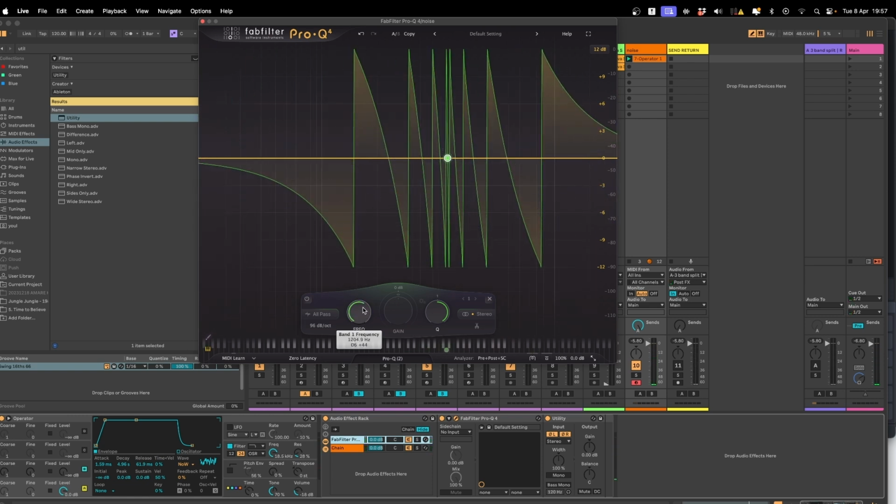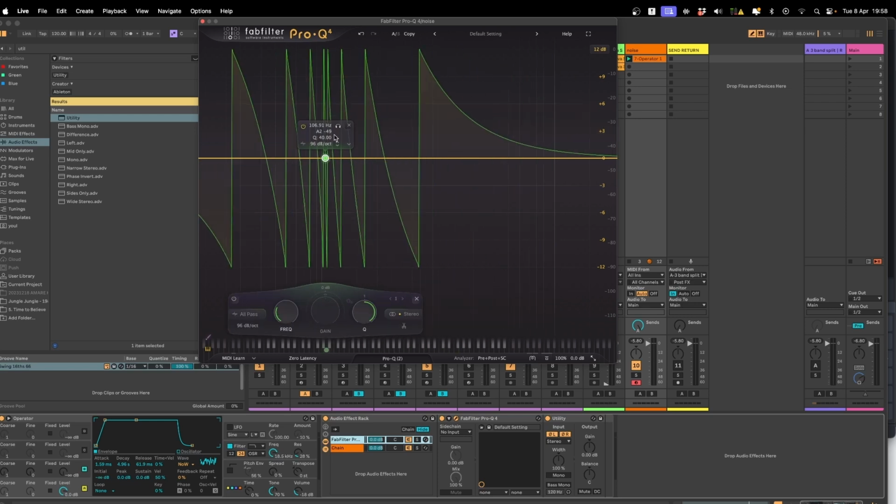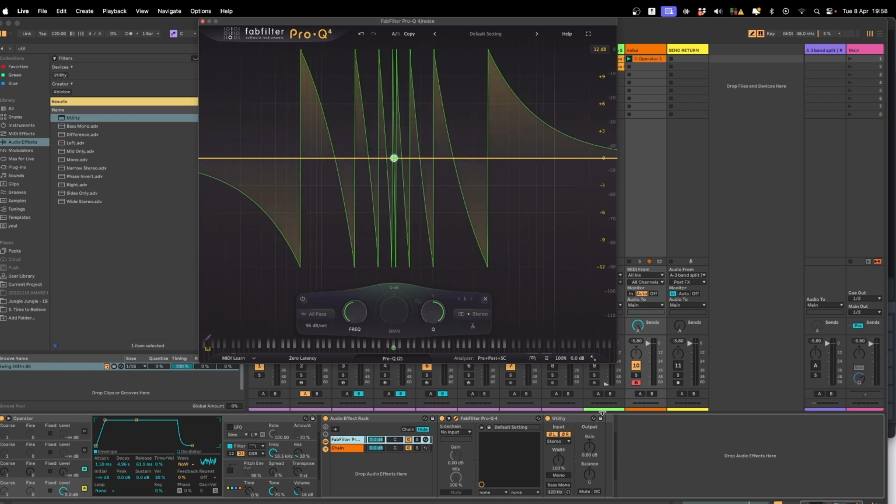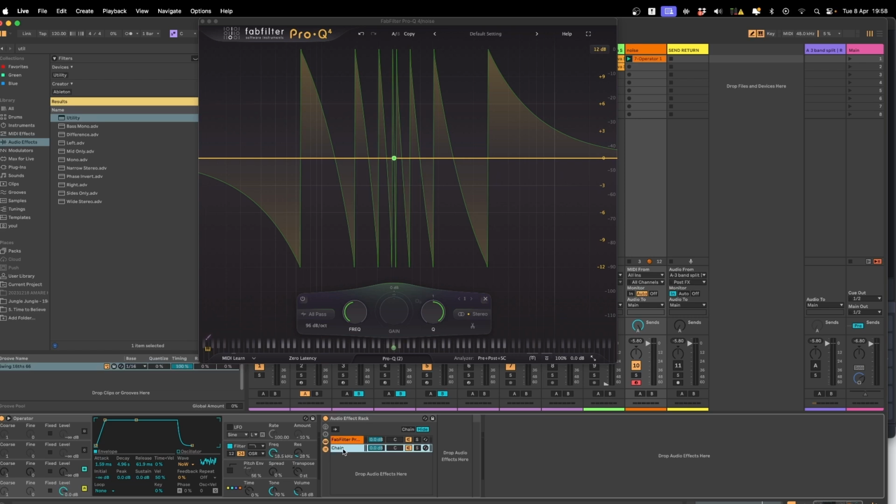It might sound silly to recreate a filter with a filter, but you see that now you understand deeply that your filters are only phase-shifting devices. We sum something that is shifting the phase, we flip the polarity, with something where we keep the dry signal, and only the phase interactions between those will give the remaining sound.